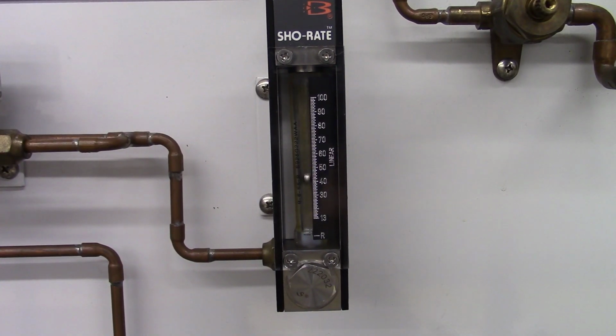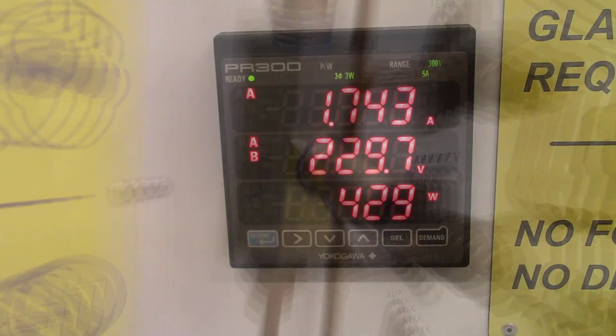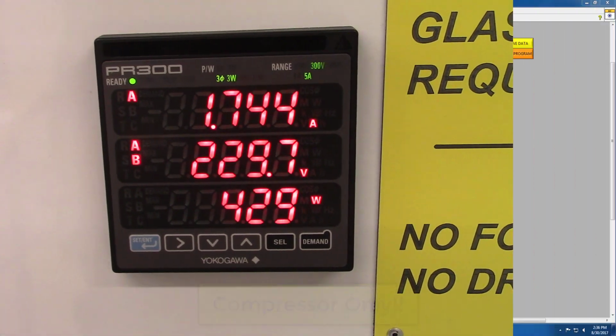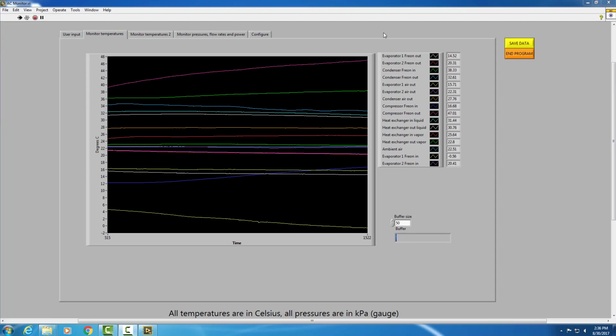Inspect the sight glass flow meter during this transient period and notice the freon is a mixture of vapor and liquid. Please note the electronic flow meter monitored by the LabVIEW is only valid when the freon is a saturated liquid. Also, please note the power meter is only applicable for the compressor, not the fans. While we're waiting for steady state, let's return to LabVIEW.